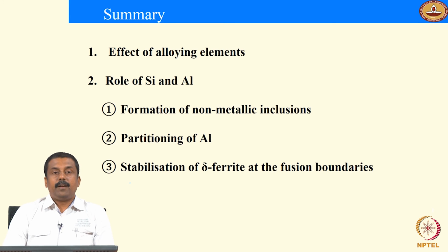Once you have a formation of inclusions, it can be turned to our own benefit. For example, as I already explained, the inclusions also act as potential nucleation sites for acicular ferrite. So if you favorably modify the size and volume fractions, you may also improve the mechanical properties of the welds by nucleating acicular ferrite, and subsequently when you form austenite in the weldments upon solidification.